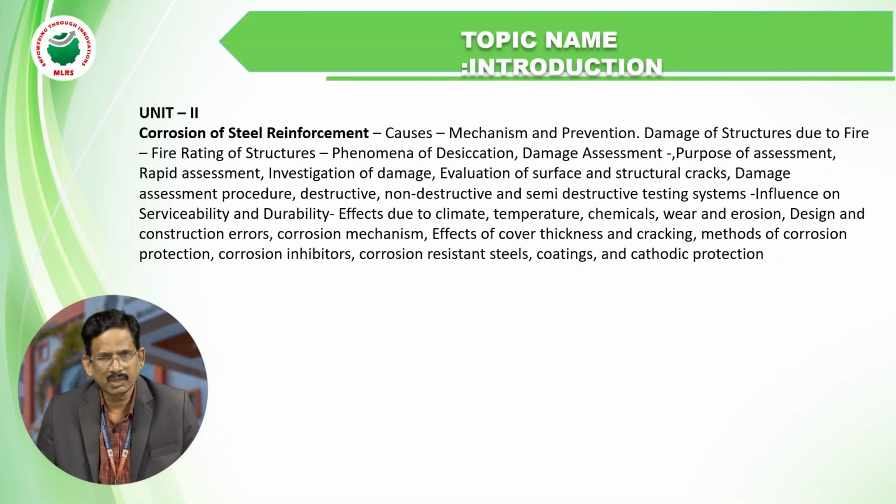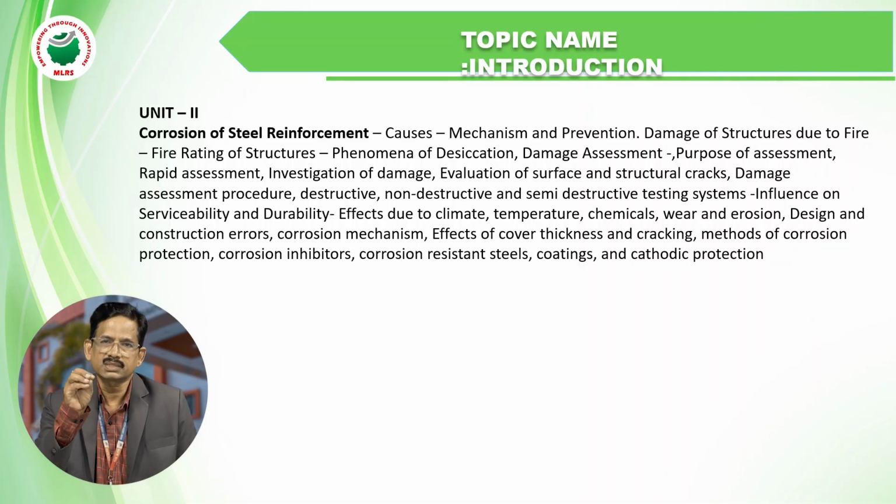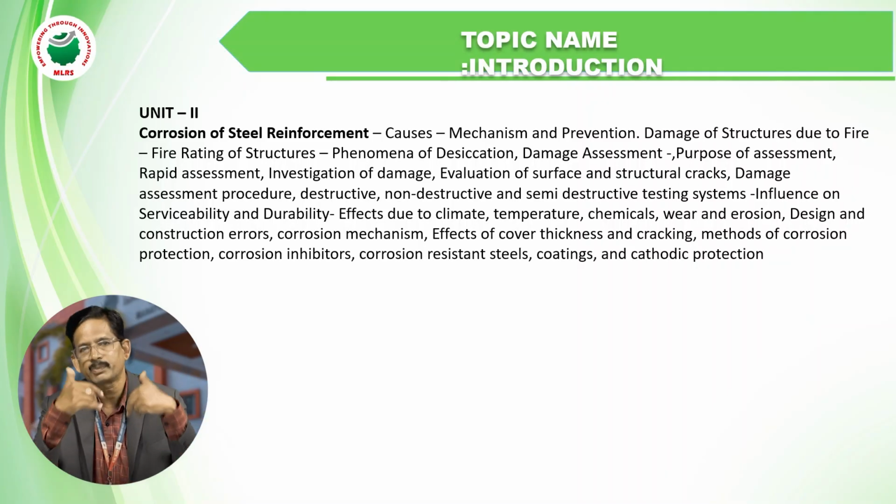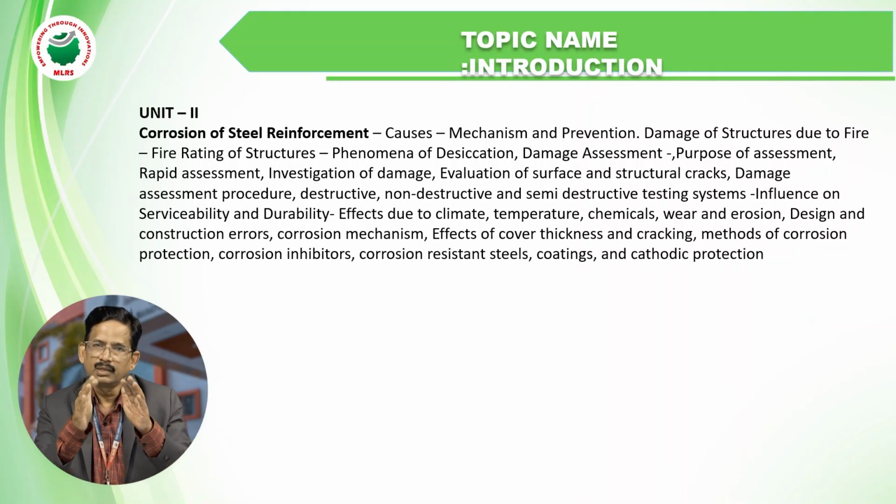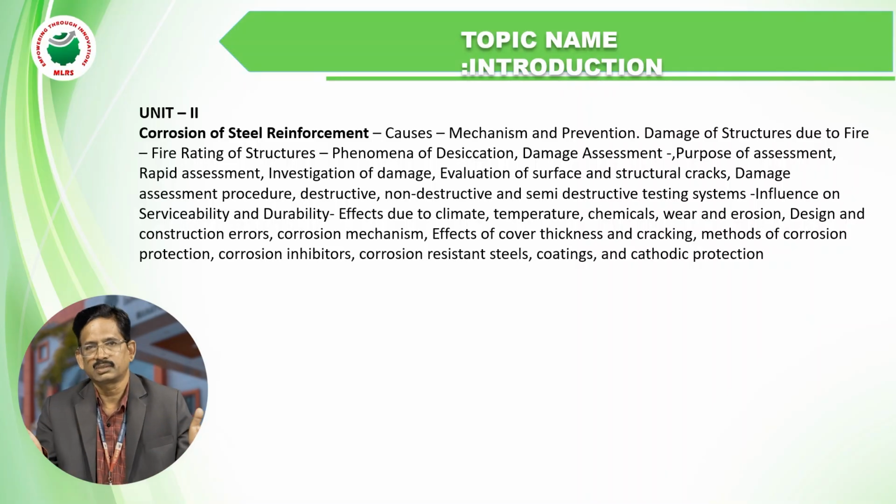In RCC buildings, we are using steel and concrete. What is the role of the concrete in RCC buildings? To take the compressive stresses only. The main purpose of the steel reinforcement is to take the tensile forces. Why? Because buildings are subjected to compressive stresses, tensile stresses, shear stresses, bending stresses, and we also face torsional stresses.